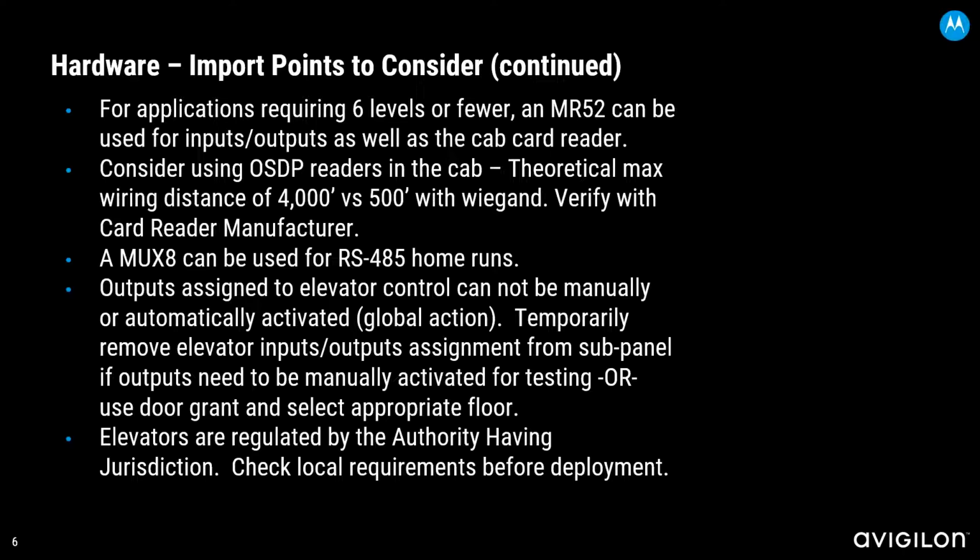Finally, I think this goes without saying, elevators are regulated, and requirements from state to state differ. I've run into a lot of different scenarios working across the U.S. In some jurisdictions, they won't allow you to mount any type of equipment in the elevator control room.